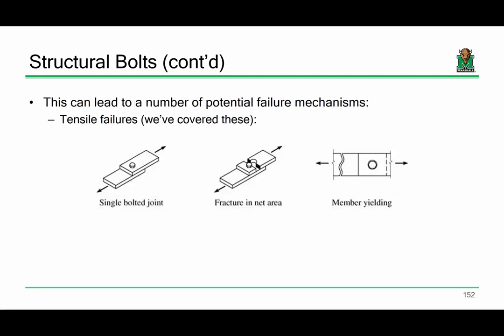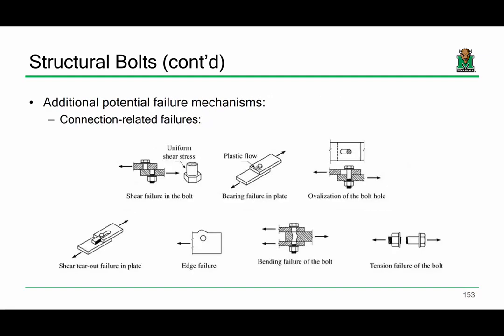Okay. All right, let's talk about the limit states that can be associated with a bolt assembly. So when I say bolt assembly, I'm keeping it simple. We're talking about a single bolt through 2 plates, yanking on them. A couple of these limit states we have already assessed and already understand. So by now you should understand that if I have an assembly like this, it could fracture through the net section, right? That's pretty simple. It could also yield through the gross section, so these are easy. Some other ones, we could shear the bolt. We could fail the plate.